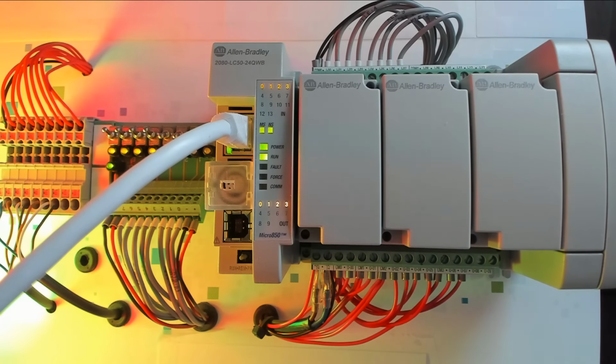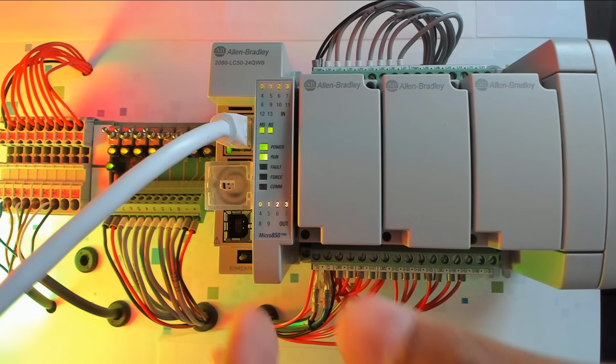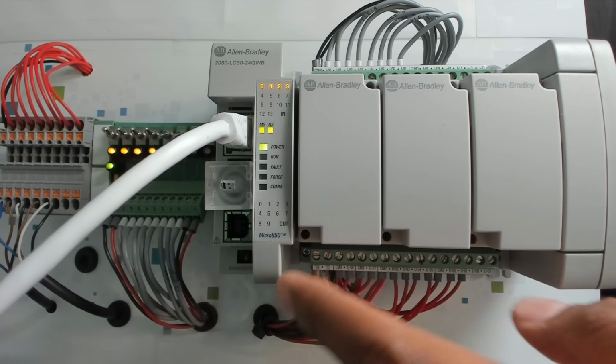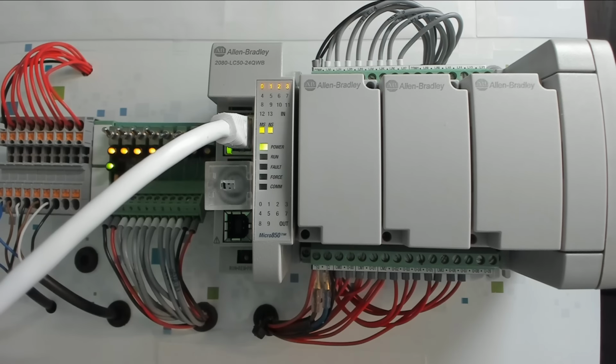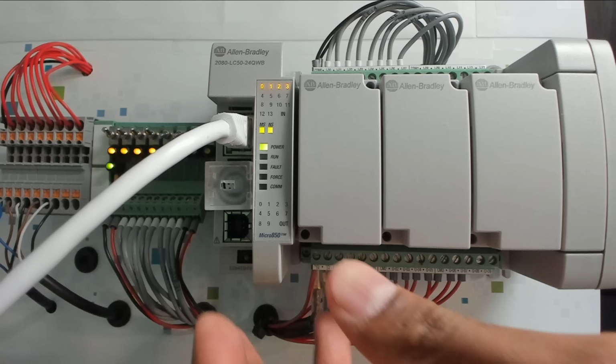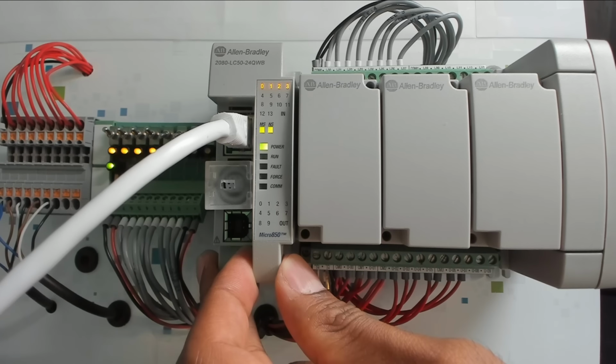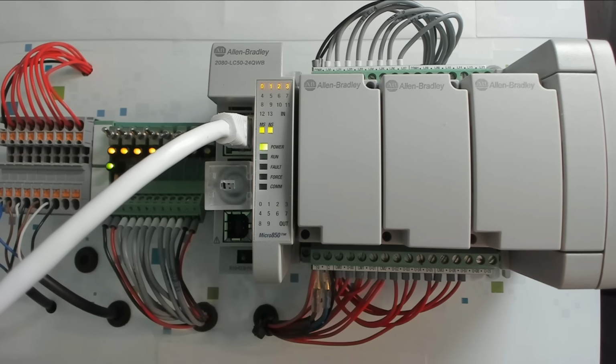So if you see this PLC again, right now it's on run mode. If I move it to extreme right, you can see PLC run mode is gone because now it's just in the program mode. It's not scanning the input or triggering the output. It's just in the program mode. So I can just program the PLC. Interesting mode is in the middle. If I put this in the middle, it says remote mode. Now in remote mode, you can decide if you want to put it into the run mode or program mode